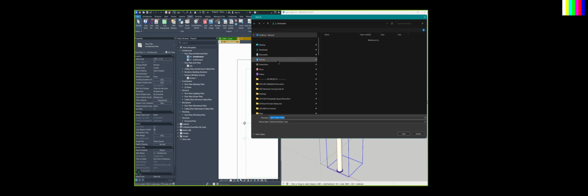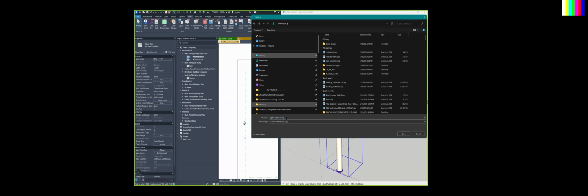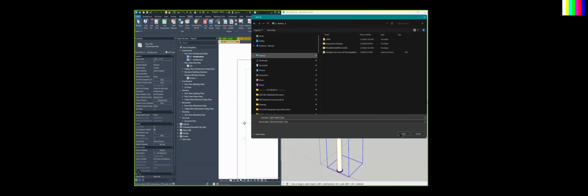And I wanted to import this into Revit. But when I go into Revit, I want to use it in my elevations and my sections and whatever. Now, this file that's here, I could save it. I'll save it as light object, to my desktop. And then when I go to Revit over here, I could go to links if I wanted to, and I could import it under CAD here.